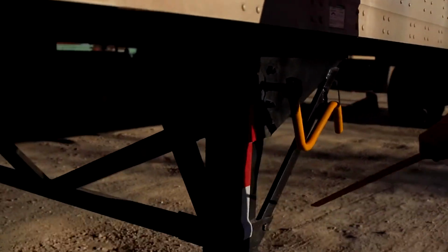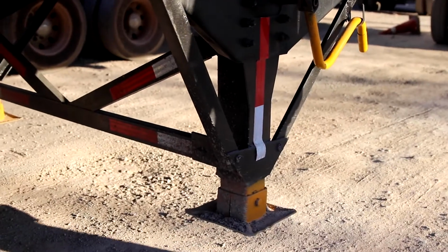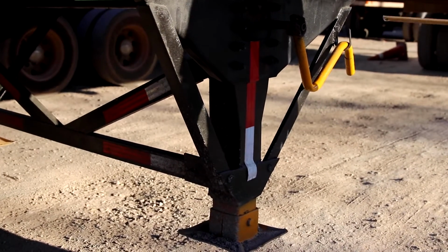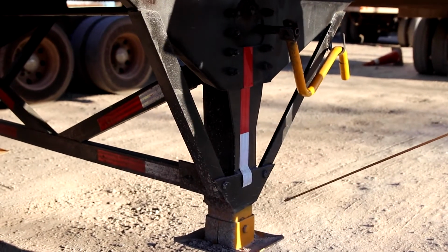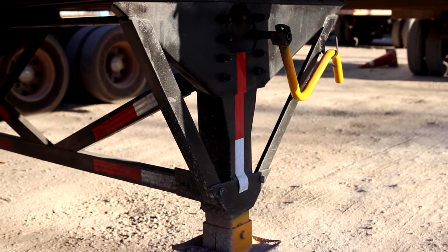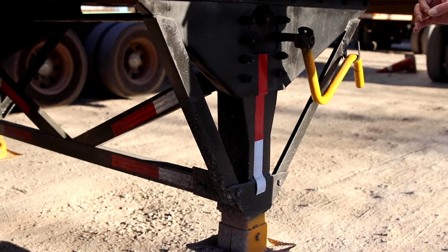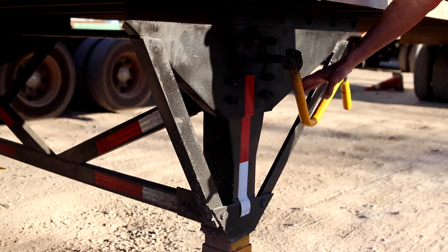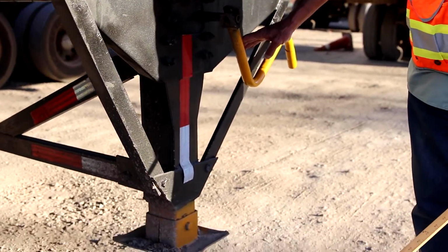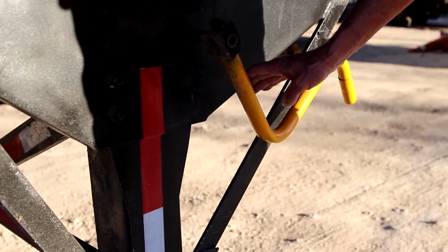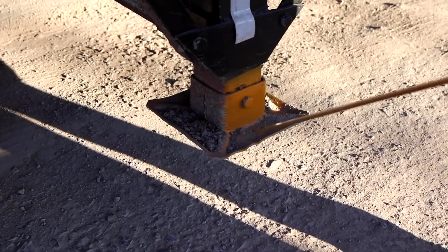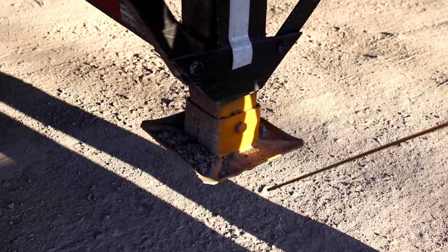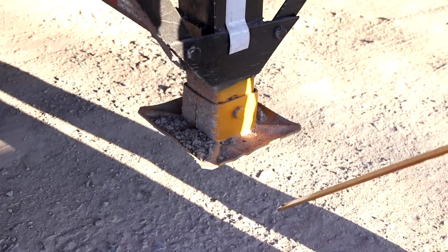This is my landing gear. It is mounted securely to the vehicle by factory welds, nuts and bolts. The landing gear itself is in the upright and travel position. My landing gear crank handle is in the locked position. There should be no debris on the feet of my landing gear, and there is some here, and it should be raised all the way up.